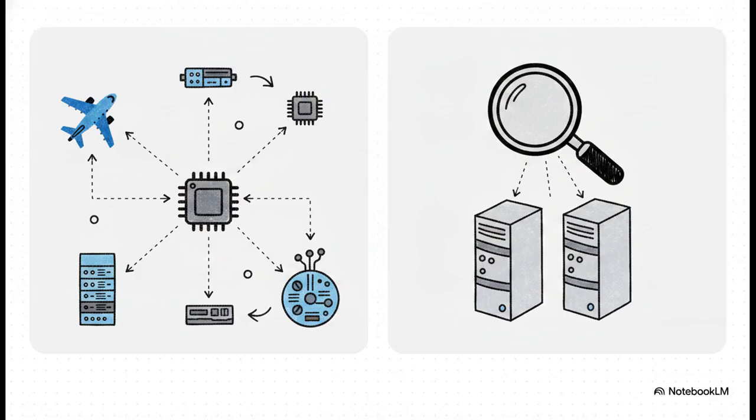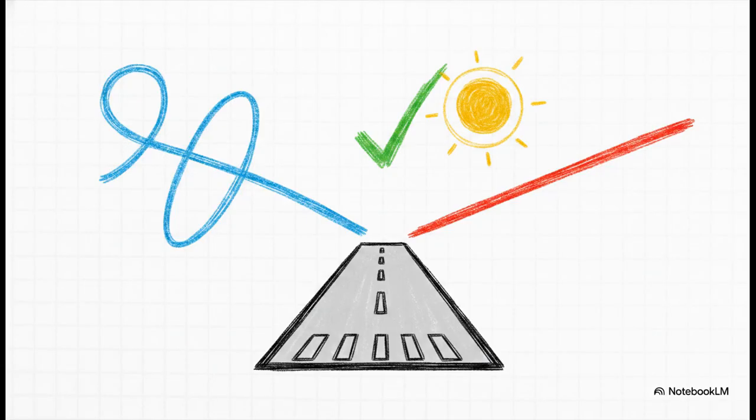Boeing, on the flip side, uses redundant hardware, sure, but they run the exact same software on all of them. The Boeing 777 philosophy emphasizes extreme simplicity and rigorous validation, actively choosing to avoid the massive complexity that diversity brings. Let's pause to emphasize a really vital takeaway here. Both of these approaches are highly successful in commercial aviation. Both the Airbus and the Boeing are incredibly safe aircraft. This proves that you can achieve highly dependable systems through entirely different engineering philosophies.